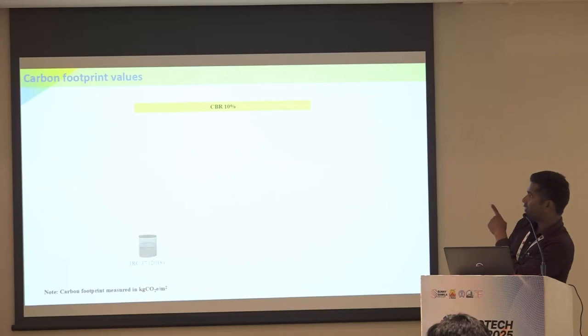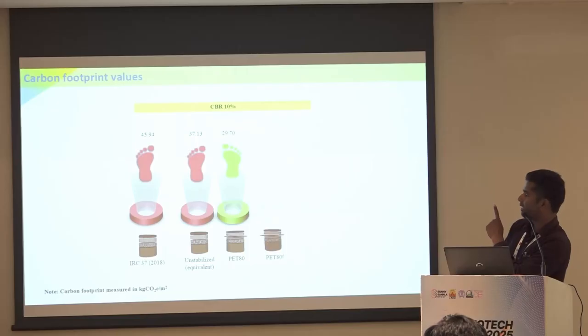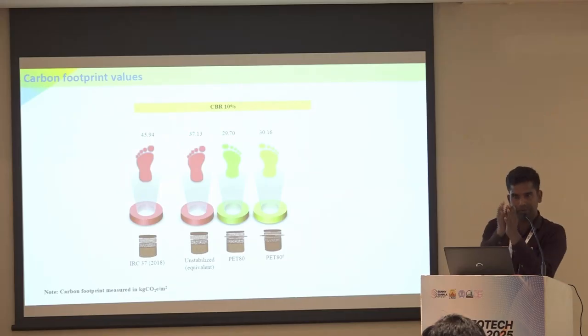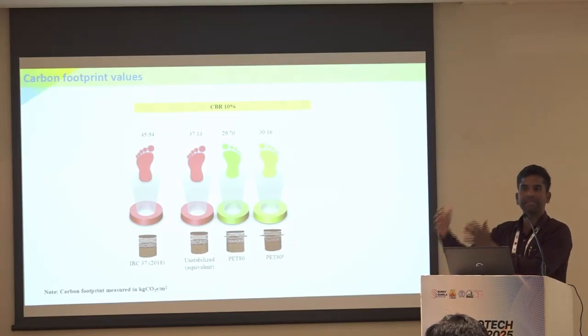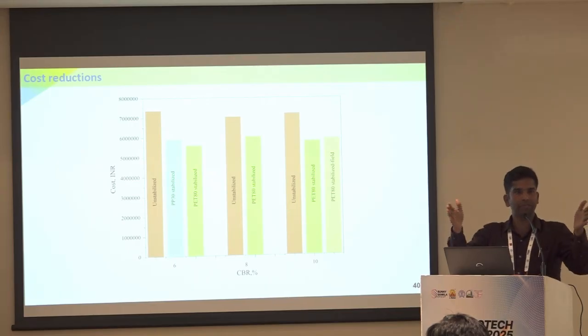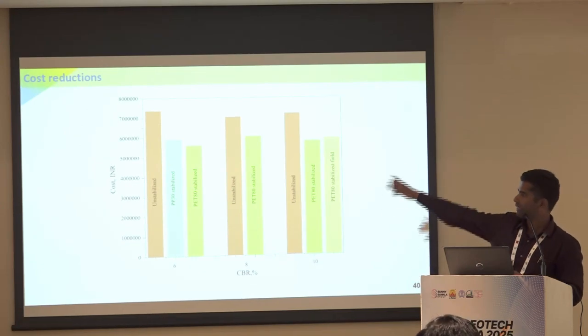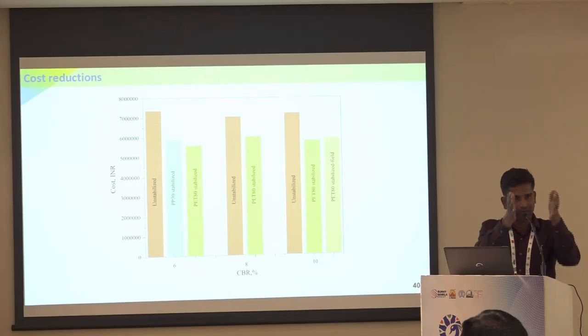Similarly, we have seen how the carbon footprints look for higher subgrade conditions. And I would say that when you use geosynthetics, we can reduce carbon emissions by at least 15% from cradle to grave. There are several stages: sourcing, placing, transportation, diesel consumption, everything. Overall, per lane of 3.75 meters, for 1 kilometer, if you use different types of geosynthetics, in the ideal case you can go up to 70 lakh reduction in a 1 kilometer length.